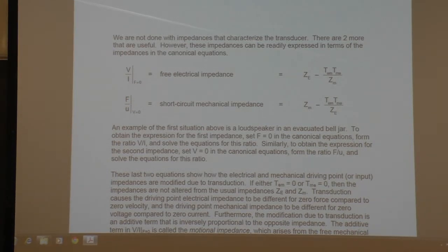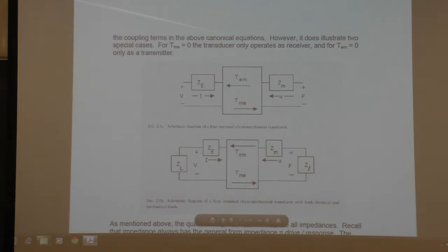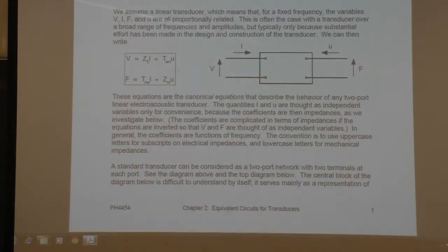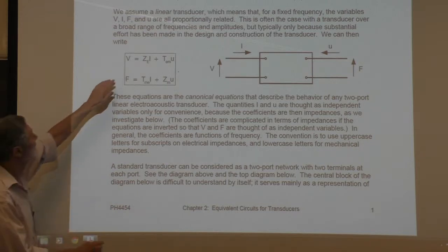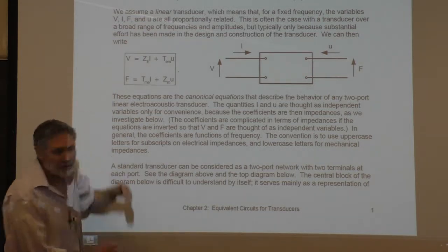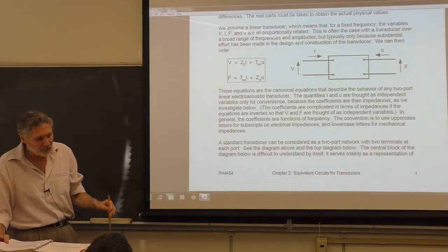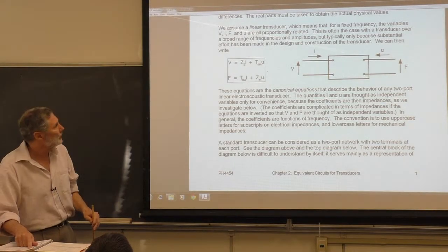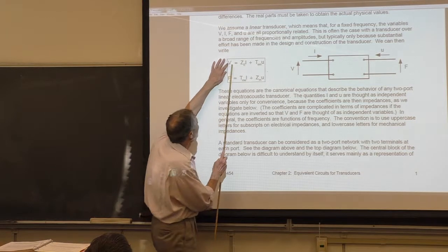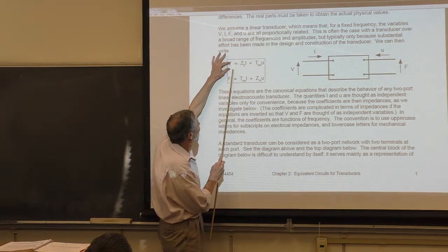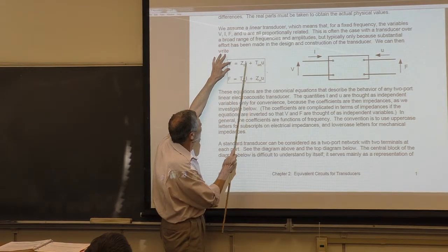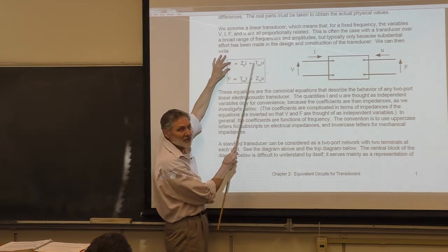And now, this takes a little bit of thought, but you can actually do it in your head. This is the electrical impedance, the voltage divided by the current for no force. So we want to look at V divided by I here, but neither of these is in general zero, right?